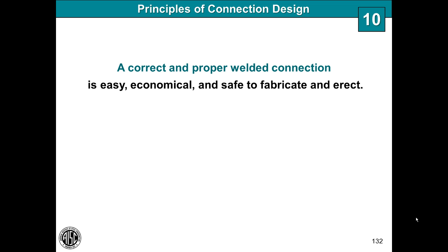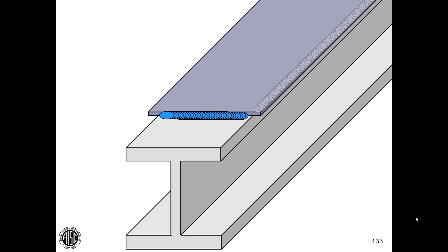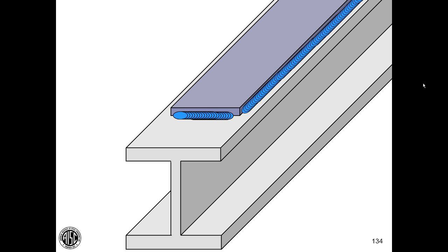In this slide, you can see that the cover plate is wider than the beam underneath. That will require a transverse weld be placed, the beam be rotated, and then the longitudinal weld made. Even if the other sequences followed, it involves flipping of the steel in order to do that. That adds time. It adds on an issue that might be concerned. Look at how much simpler the job is for the fabricator if the cover plate is simply detailed to be more narrow than the rolled beam. A simple, easy to fabricate assembly that works just as well.